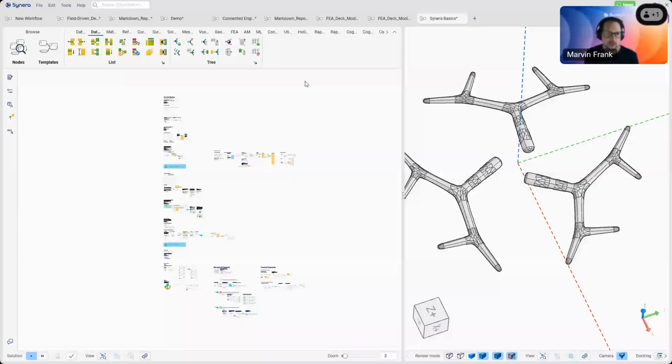We import a very basic design of this mounting or bearing, and then we will create an FEA setup. We will do topology optimization, and we will do an automatic reconstruction of that. But as you can already see with some variants, there's also a design of experiment involved, having different design variants and calculating these design variants up front. So in the end, we end up with this. Here it's only 3. You could also then at home add more design variants. So let's go through it.